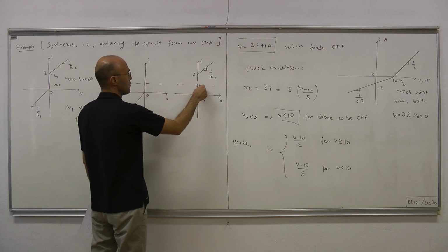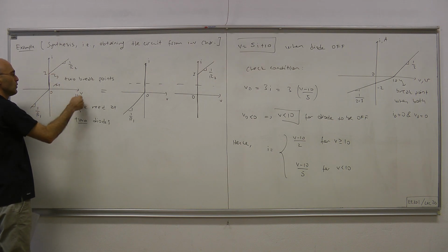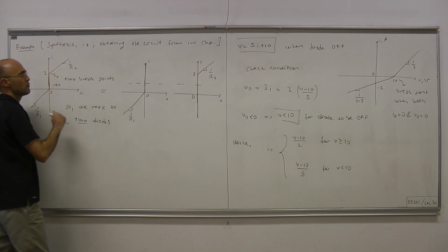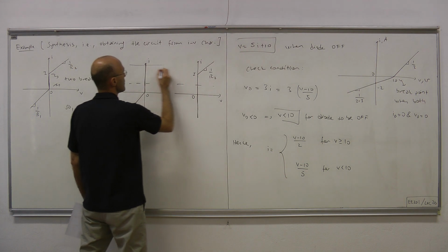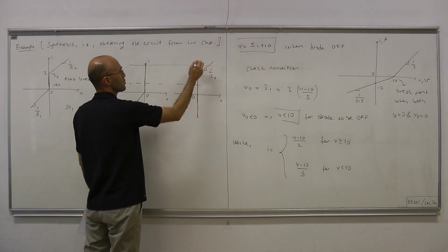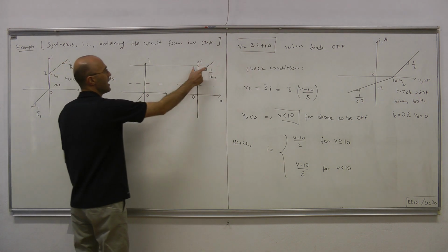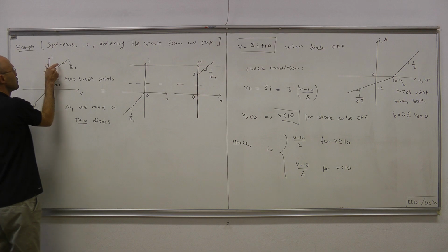The voltage contribution of this guy is also 0. Therefore, whenever the current is between 0 and I, the corresponding voltage is 0. If you pick something a little bit larger, the voltage contribution of this guy is still 0. The voltage contribution of this guy is this amount, and then the overall voltage will be that amount.